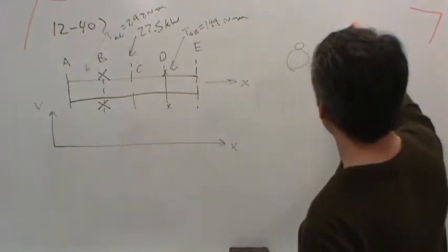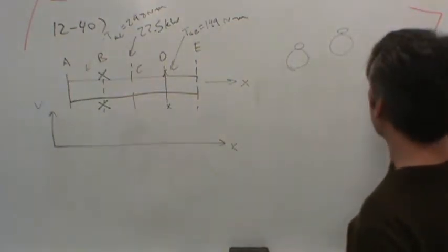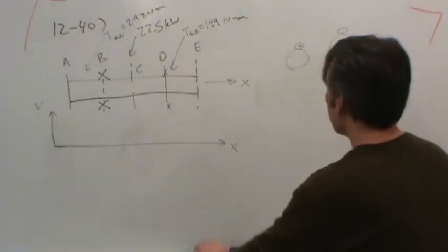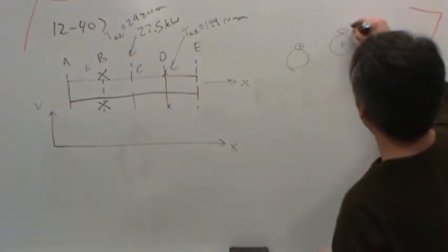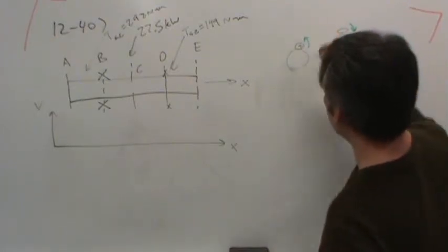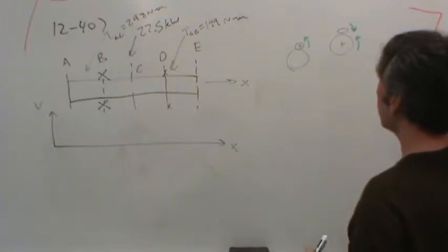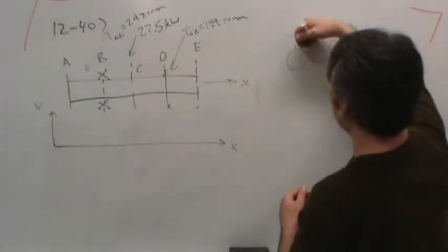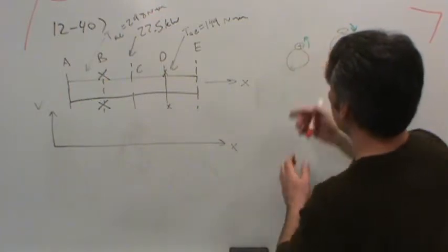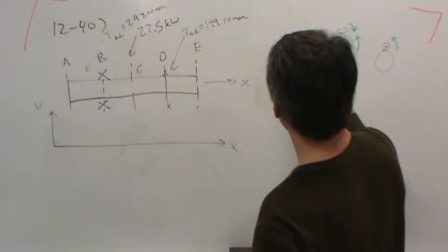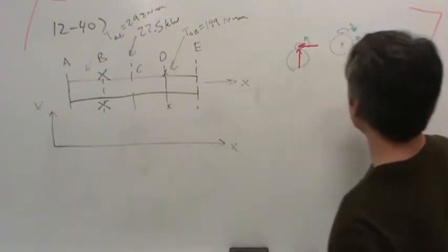Here we had a large gear here, small gear here, and let's see, rotation directions. Q rotated in this direction, so all of our gearing rotated counterclockwise from our view. And so the loads on the shafts ended up being, let's see, if it's rotating this way, there'd be force in this direction. So on the shaft itself, we ended up with loads like this.